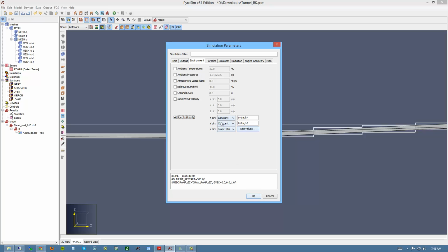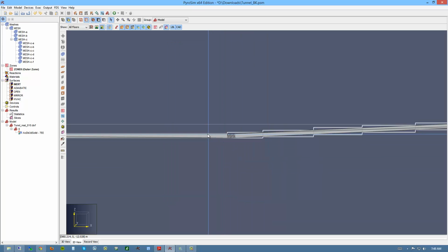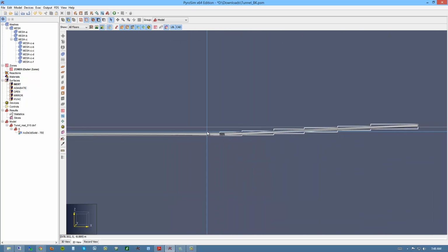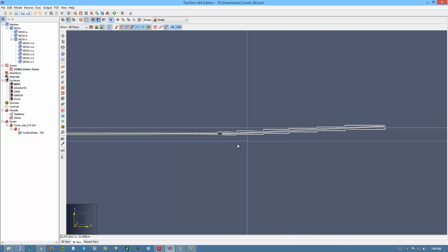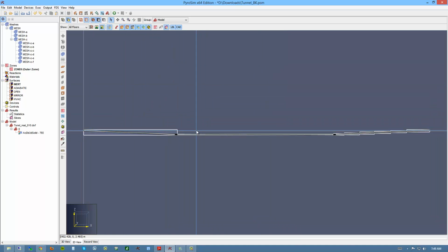by using gravity ramps. And then you would have just one mesh that went from one end to the other that was fit perfectly to the tunnel, didn't have any extra gaps, and as your flow would flow through this portion, the gravity angle would change and the buoyancy force would change the buoyant force and flow up the tunnel like it should. So that's another option without having to do your geometry, sort of to reflect the real world, and to use a little bit more computational efficiency. You can do it like that.